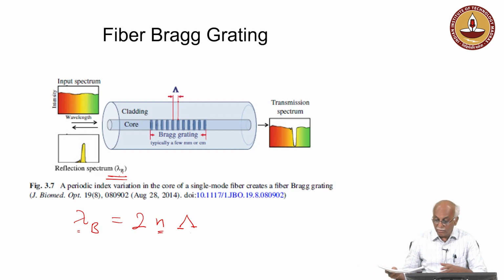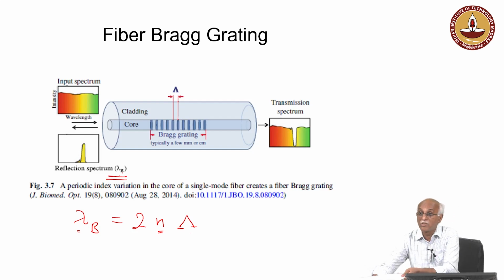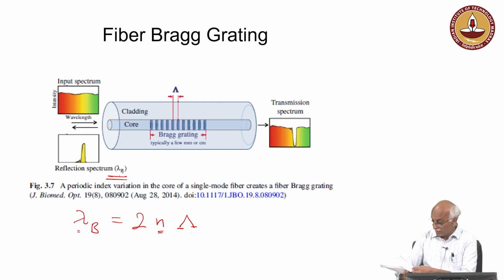So, if I mount a fiber Bragg grating on a tissue structure, I should be able to capture the change in the tissue temperature. In some applications, for example, in hyperthermia, meaning the development of systems where radio frequency induces heating of the tissue, we want to capture the temperature information even when heating is taking place.